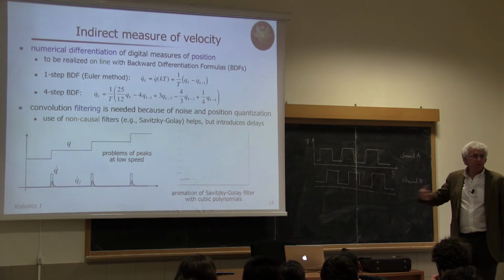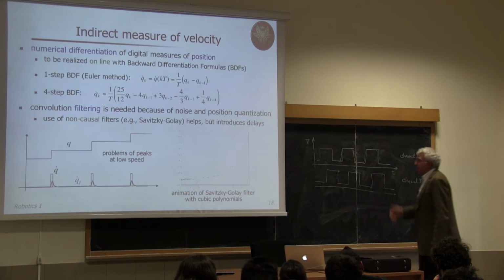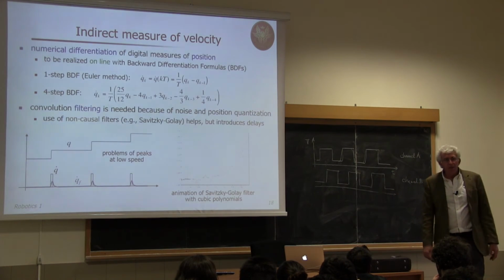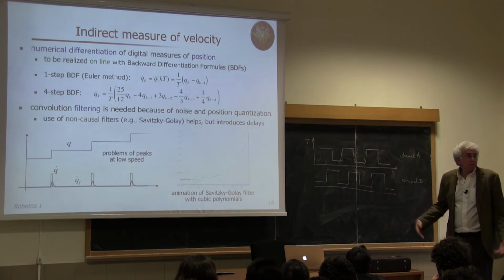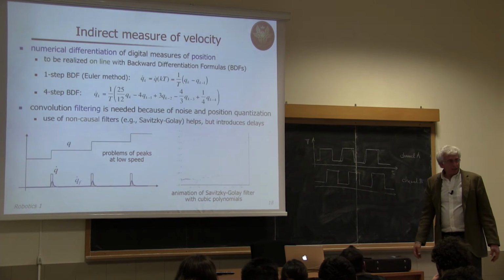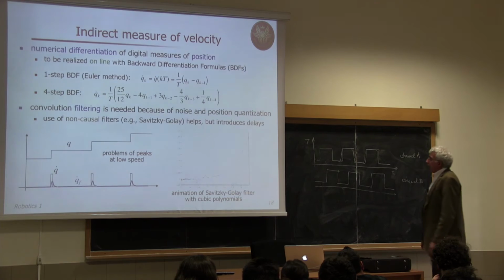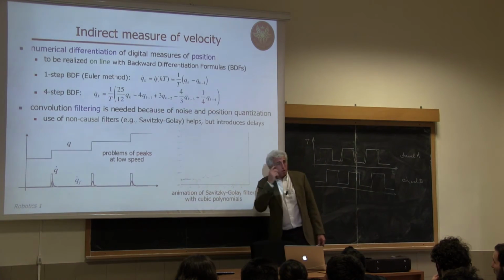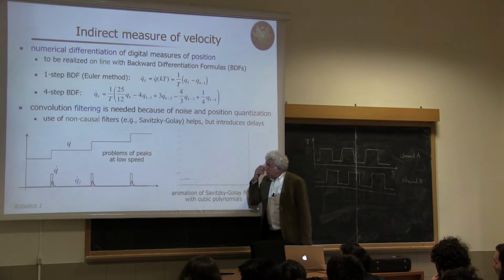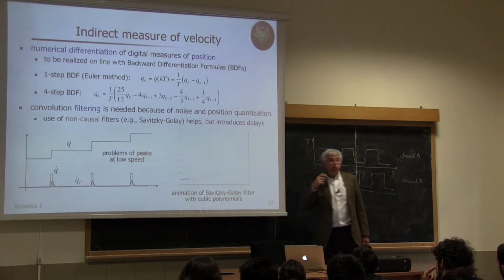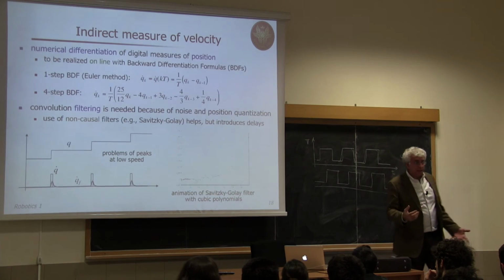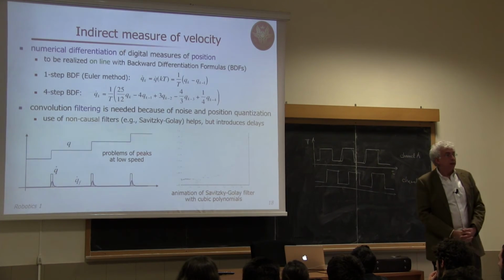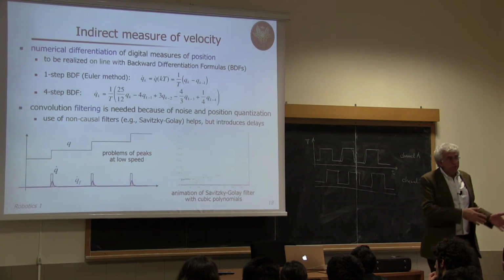If the trajectory is not smooth, if it has sharp changes, sharp accelerations, then the older samples are completely useless. In fact, this is a general problem. If you don't know in advance the signal that you want to differentiate, in our case the position profile, then you can only use previous samples.